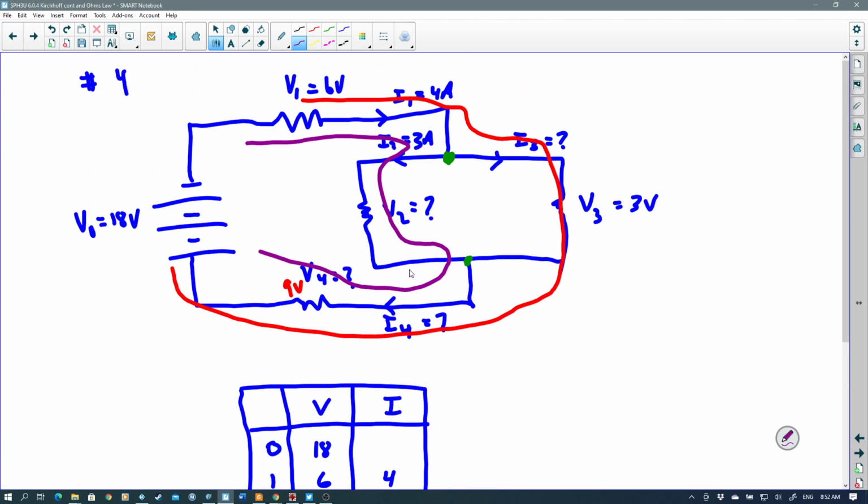Well, I just realized there's no I0 that is being asked in this picture, unless I forgot to draw it. No, there's no I0 being asked to draw, but I0 and I4 are going to be the same as I1, because if you look at how the circuit is drawn here, I0 would be right here. So what is the total amount of electrons going through the battery, basically? Well, that has to match the total amount of electrons in this path here, which is counted as 4 amps. So we know that this is actually 4 amps as well.